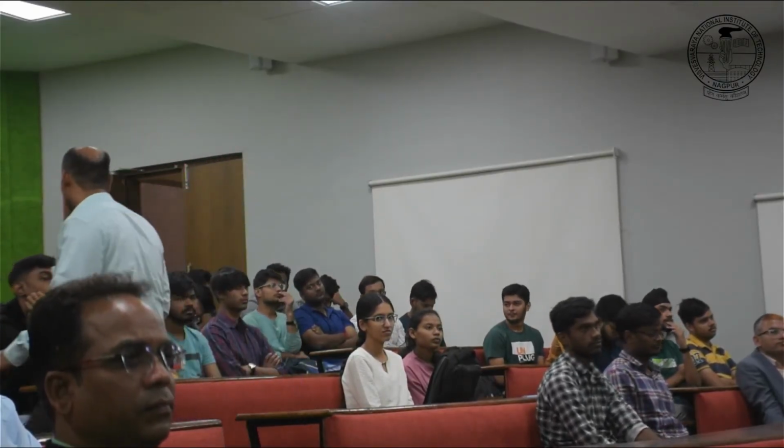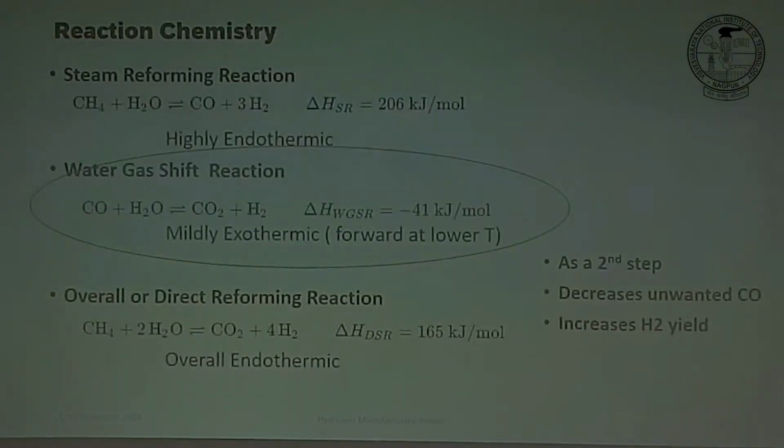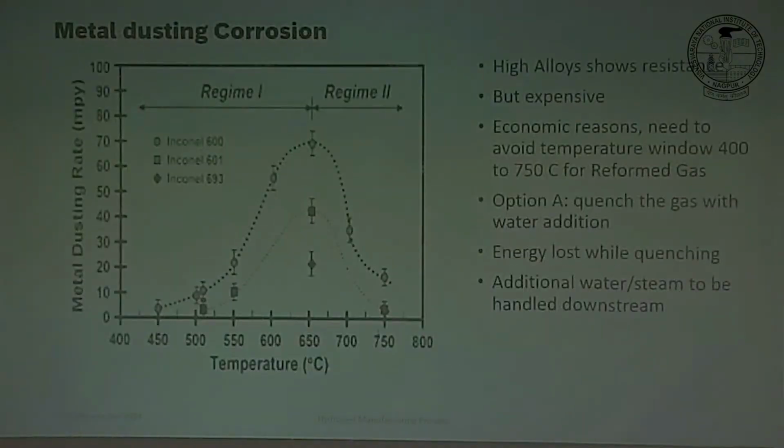Now at 360 degrees there is still a lot of energy left in the gas, right? What we can do is further cool this gas and preheat the feed and air. So that is another step in heat integration.